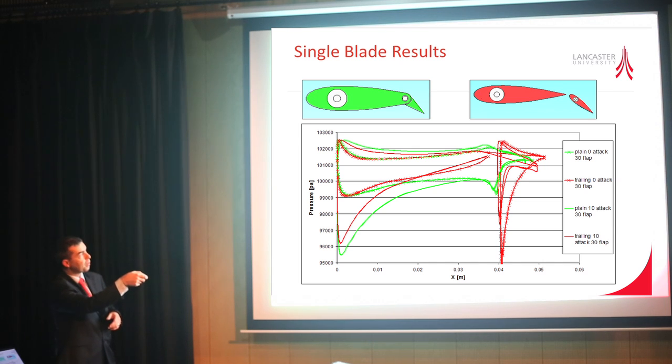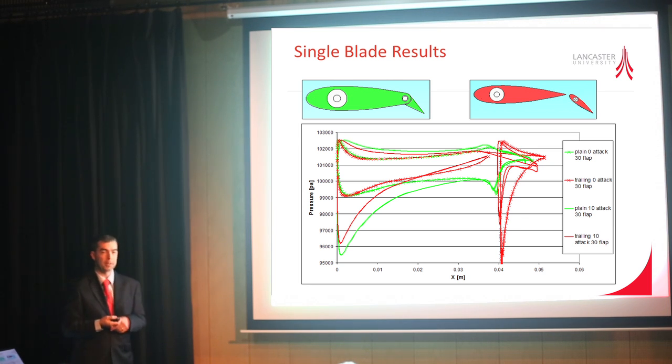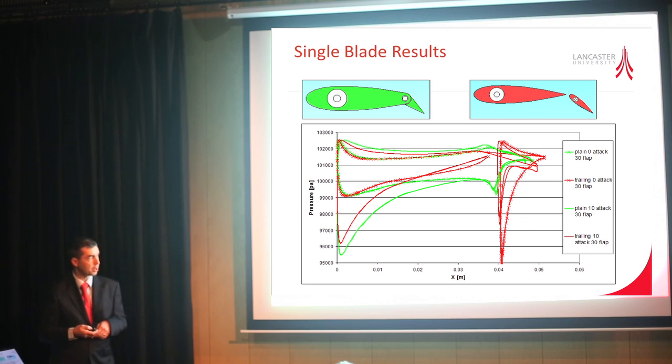So we want to avoid that. Although we know the slotted arrangement is better in terms of overall performance, this peak here, where the lower pressure occurs, is potentially damaging. So there's quite a lot involved with optimizing these systems so that we don't cause cavitation, depending on the flow condition.